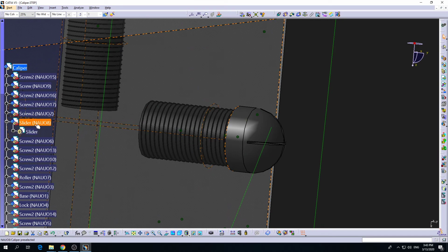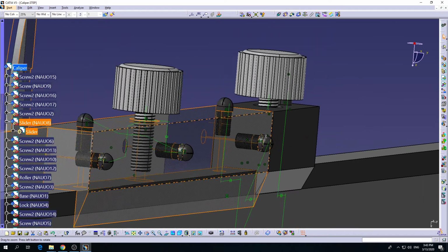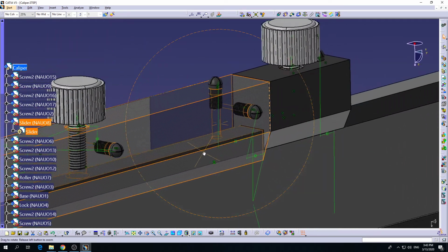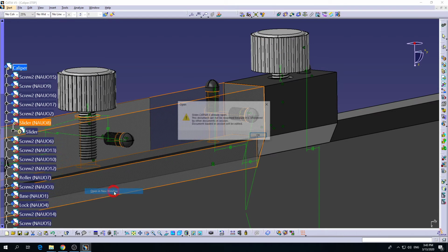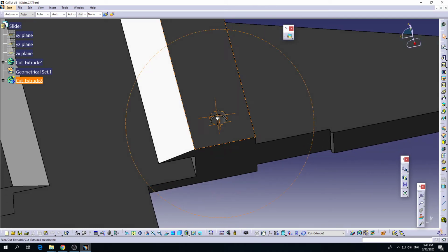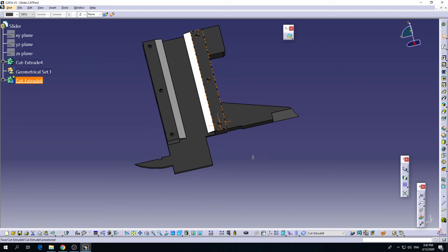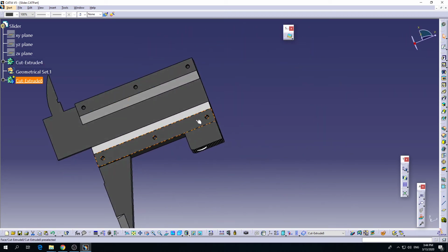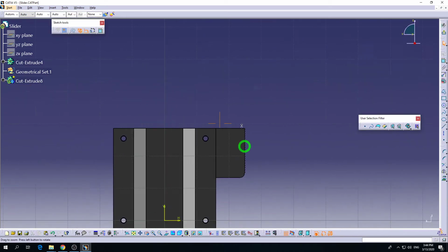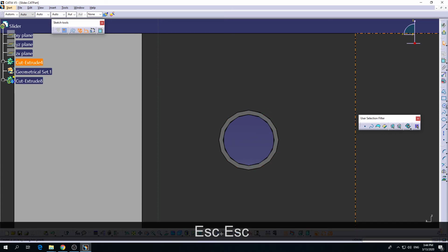So I can make the cut in the slider model a bit larger, so I don't have that collision. But since this model wasn't created within Catia, let's see. So this will be that area. If I check the diameter, it's 0.762.